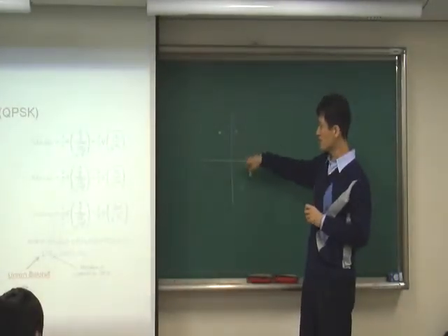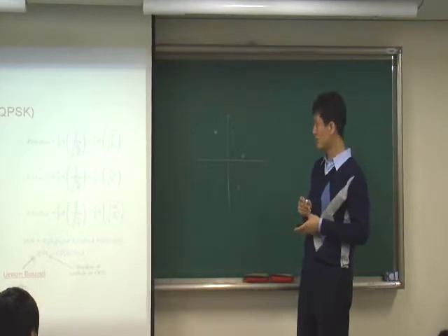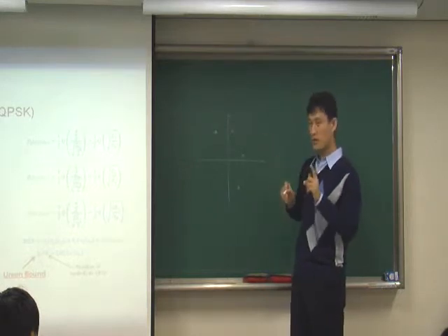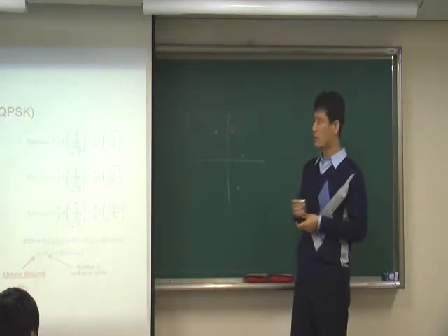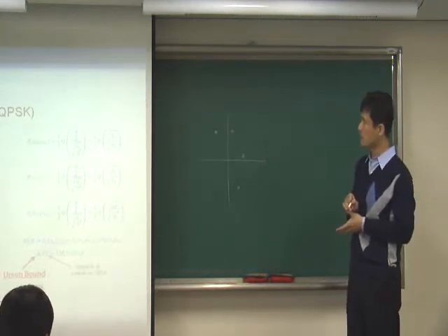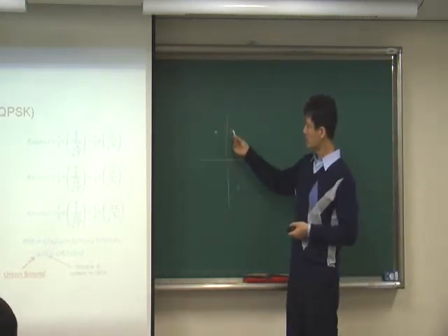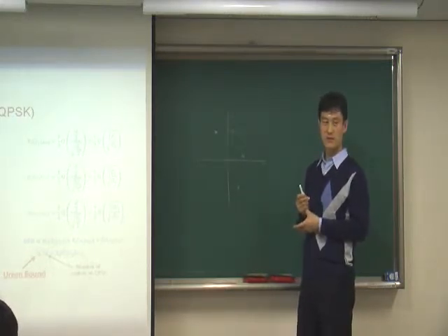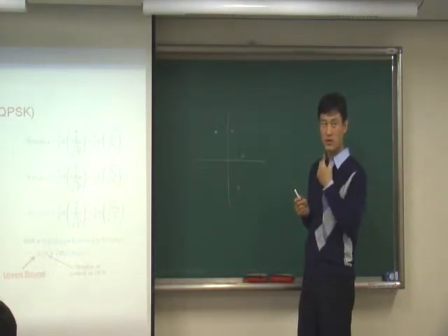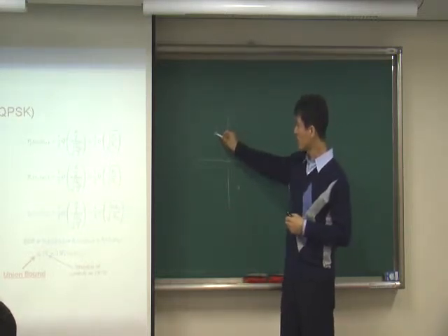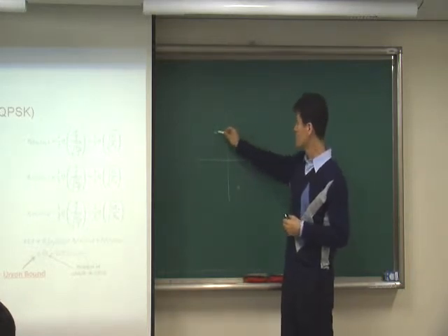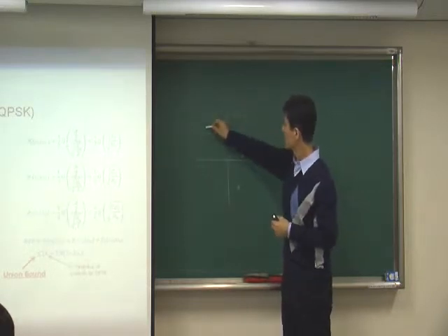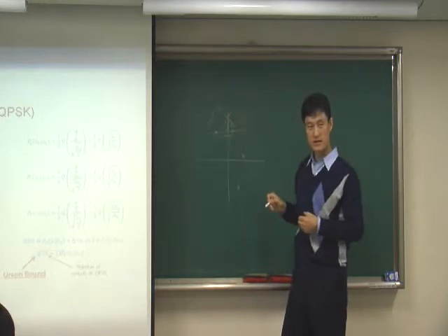If you consider each of them separately, then it's a lot of work. So what typically people do is that you pick one error case with a higher error. Which one gives you the higher bit error rate? This is case 1, 2, 3, 4, 5. Which case gives you the higher error probability? Case 1, right? Because case 1 has a smaller distance. Smaller symbol distance gives you highest error, right?